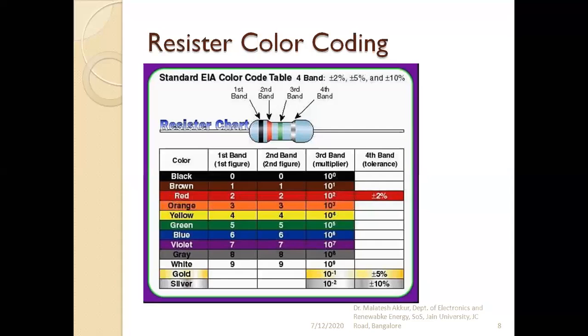One popular line is: "BB Roy of Great Britain has a very good wife." There are many other sentences like this. The first letters start from black, brown, red, and so on, and each corresponds to the digits 0, 1, 2, 3, and so on.